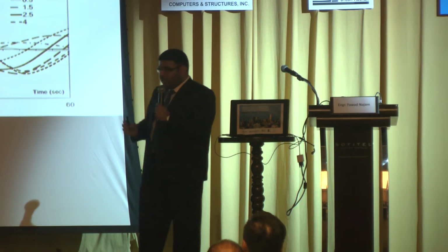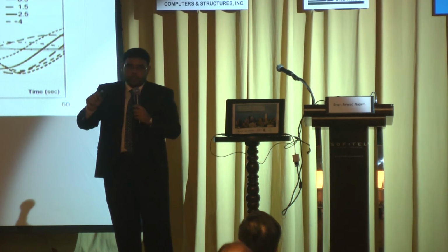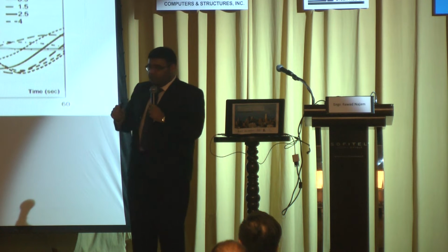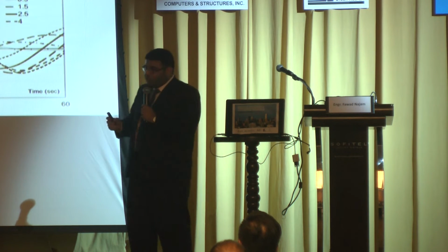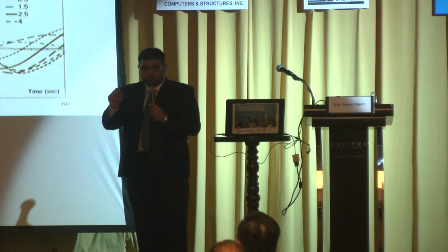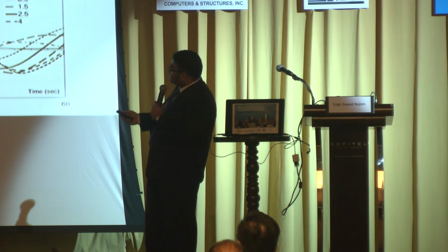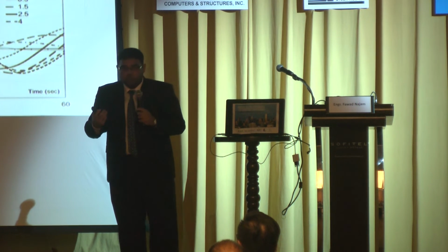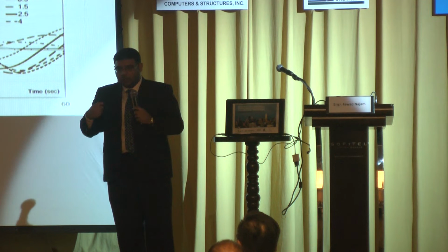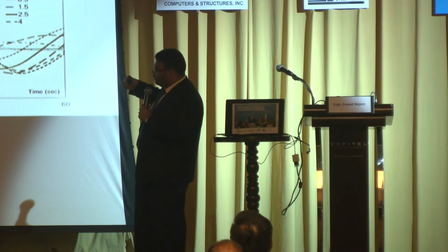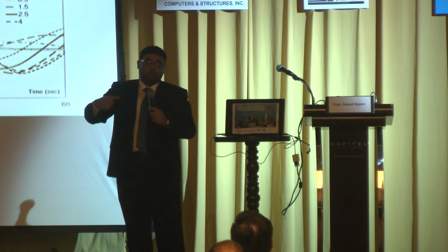Just to give you an example of period elongation, when a single degree of freedom system enters into nonlinearity, its period elongates. And just to show that it is a real phenomenon, not a conceptual idea, what I did is I separated the first mode history response of the 44-story case study building, which I showed before, and I applied scale factors to the ground motions.